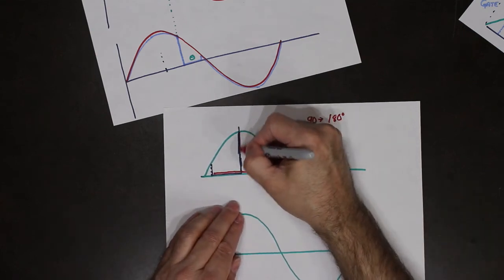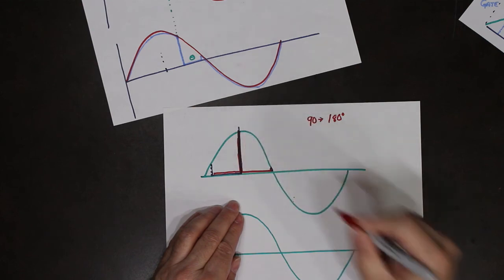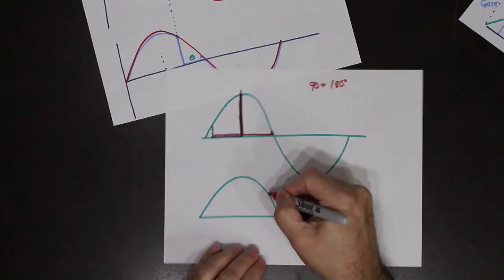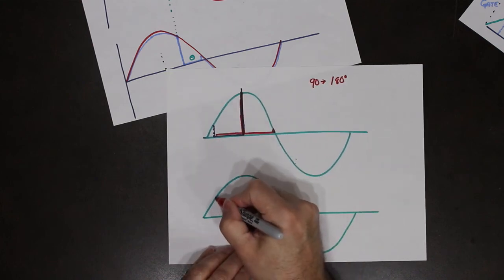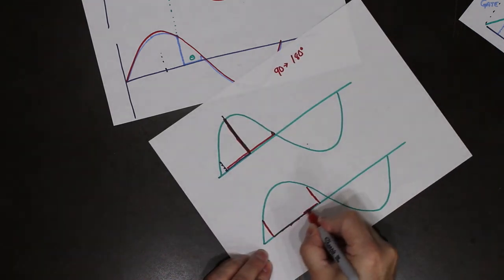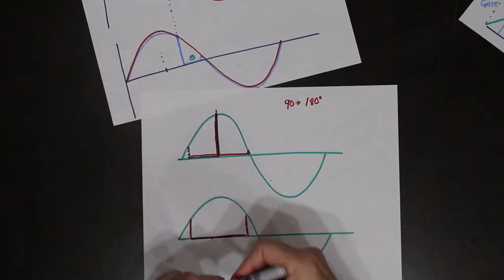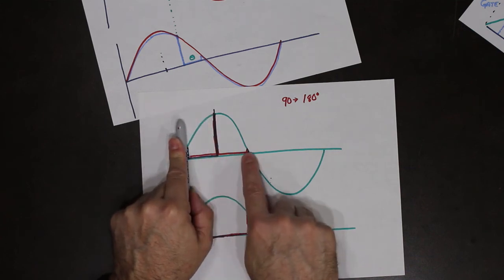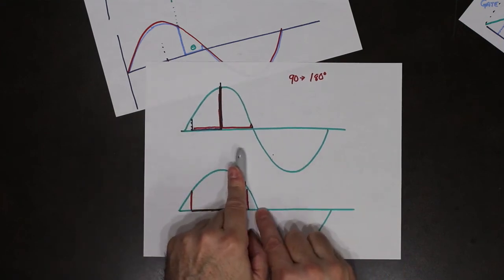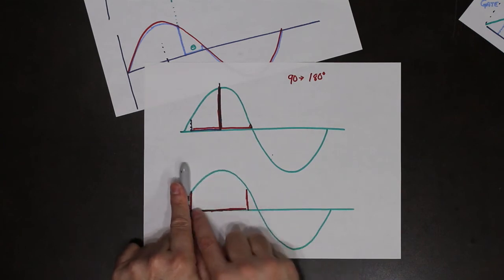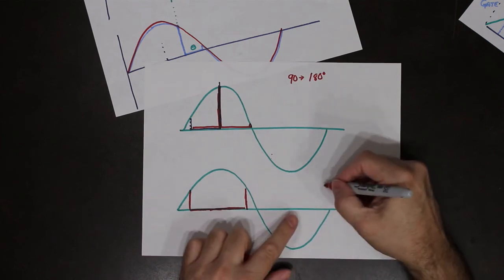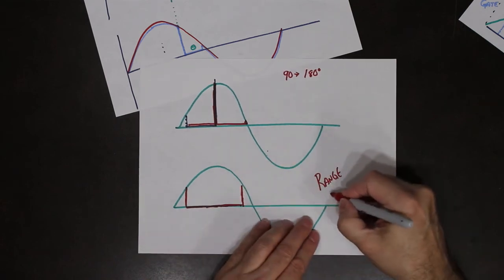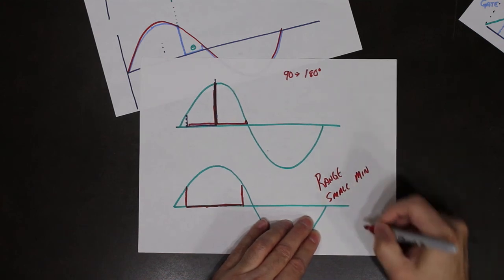Okay, now this is the point at which it turns on. That's the minimum value right here. In this one, the minimum value is here to about there. So remember, here, this is the conduction angle, and if I slid this point over here, this is the conduction angle. So now, I'm going all the way over here. This is the conduction angle, and I can adjust it all the way over here to this is the conduction angle. So this one has a larger range. Also, you can actually get a smaller minimum conduction angle.